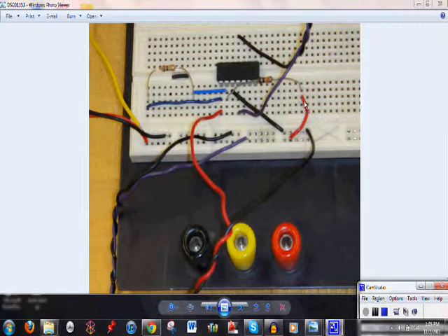And then here we go into the first resistor, which is a 10K, and that runs into the inverting pin on the op amp. And then the wire goes from there to the 100K resistor, which then goes to the output. And with the output, we have the other DAQ wires connected, and this measures the voltage after the first resistor. And by dividing the output by the input, you can get the gain on the op amp.